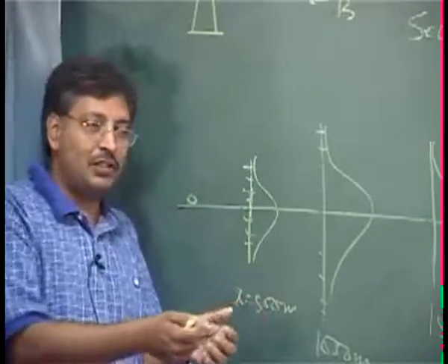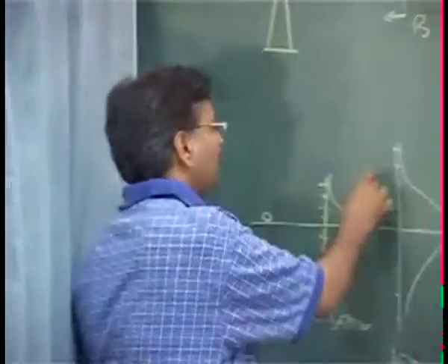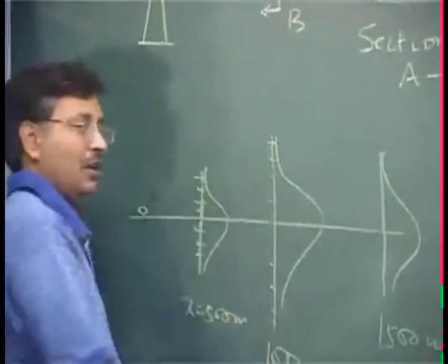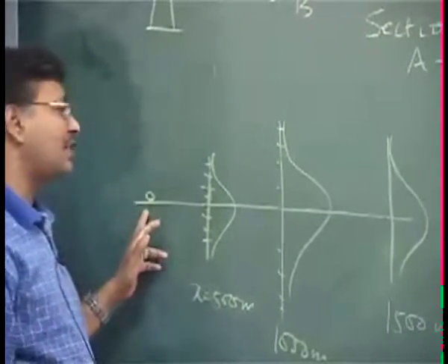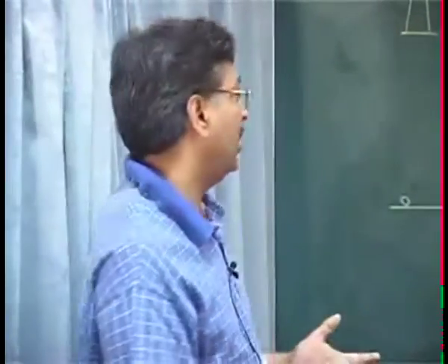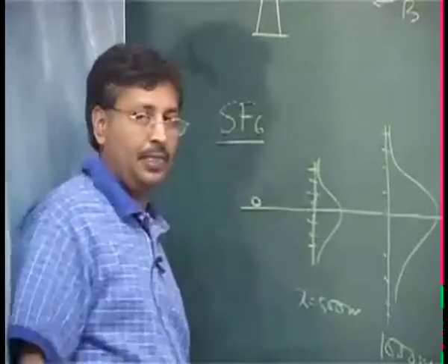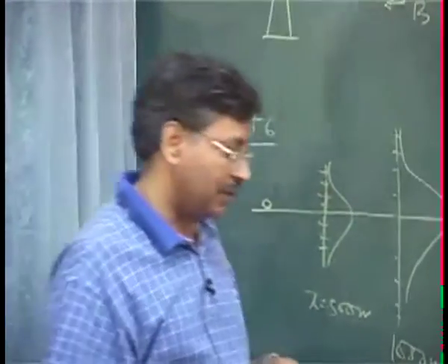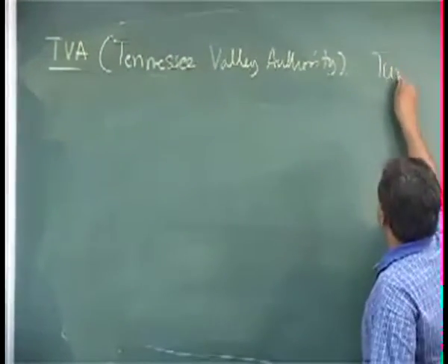So they go into the fields with some small handy gas chromatograph or whatever instrument, and they measured at different places of Y, and they have to measure at the same time. Suppose 10 people can stand with their monitors, and then they release some tracer. I don't know what tracer they released, but the normal tracer that we use in air pollution study is SF6. The person involved was the same person who talked about stability, that was Turner, and his team.